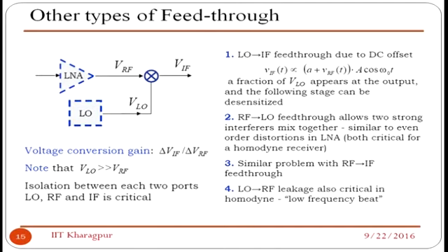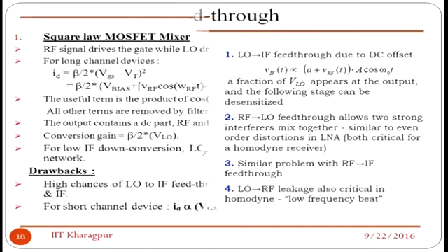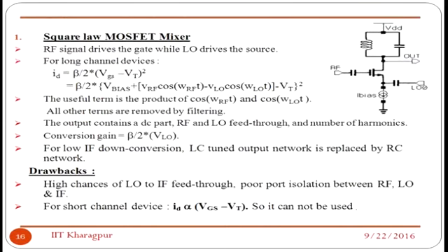So this is the typical problem of mixers. So isolation from the low frequency domain to the high frequency is a very, very important and critical parameter of any mixer design. Coming to the implementation types one by one, I want to design a mixer. Already I have understood that I want transconductance modulation in series with a switching circuit.